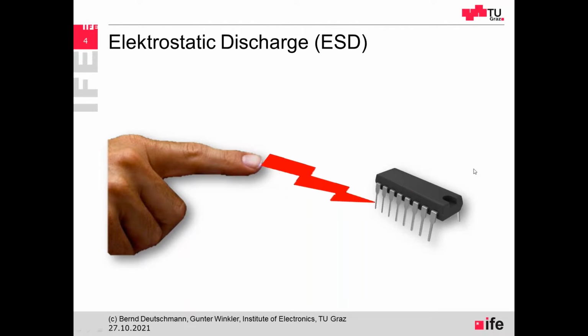Okay, so today we would like to talk a little bit more about electrostatic discharges in relation to microelectronics, and especially why we should be careful when we are touching integrated circuits, as you can see here on the screen. When a human person that could be charged up to a certain level is touching an integrated circuit with the fingers, very often there is a disbalance between the charges, and we can generate some electrostatic discharges from the human person into the microelectronic system.